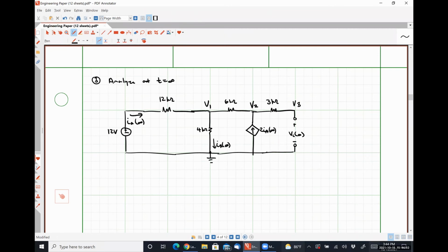But because I recognize that no current is flowing through the 3 kilo ohm resistor because it's not part of a closed current carrying loop, V2 as it is drawn and V3 represent the exact same voltage. So that's why I am choosing to ignore this node over here, because I know that the voltage drop VC will be the exact same thing as my nodal voltage V2. Adding that extra variable just complicates things. Does that make sense?